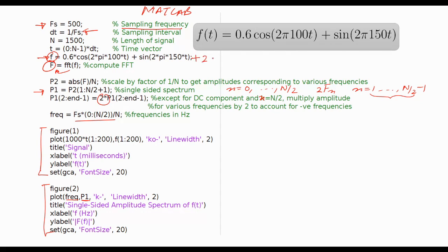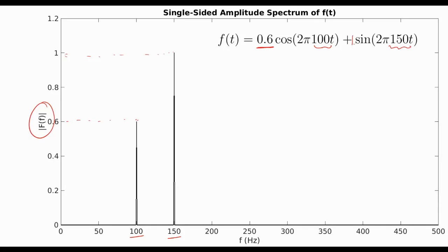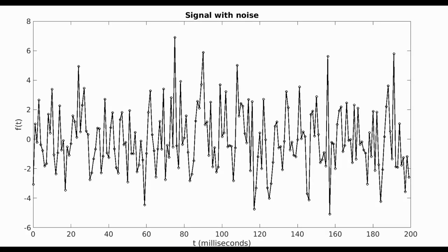Next, we can add to our code some random noise using an additional function, the random function. Then we have a signal with noise, because a typical signal in an experiment would be accompanied with noise. And if we have such noise, now you'll see the benefit of doing DFT or spectral analysis: we can't understand what frequencies this signal has because it looks fairly random to me.